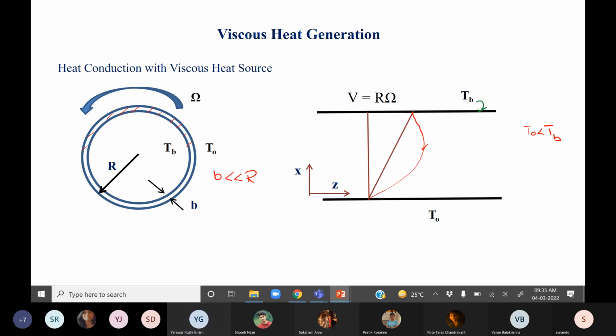Pressure-driven system. If you do not have any viscous heat generation, then what you have, using the terminology of momentum transfer, would be simply Couette flow. The velocity profile would be linear between the bottom plate and the top plate. If you have a pressure gradient imposed on it, then the linear part is going to be disturbed, and you may get a velocity maximum, Vmax, in between the moving top plate and the stationary bottom plate.